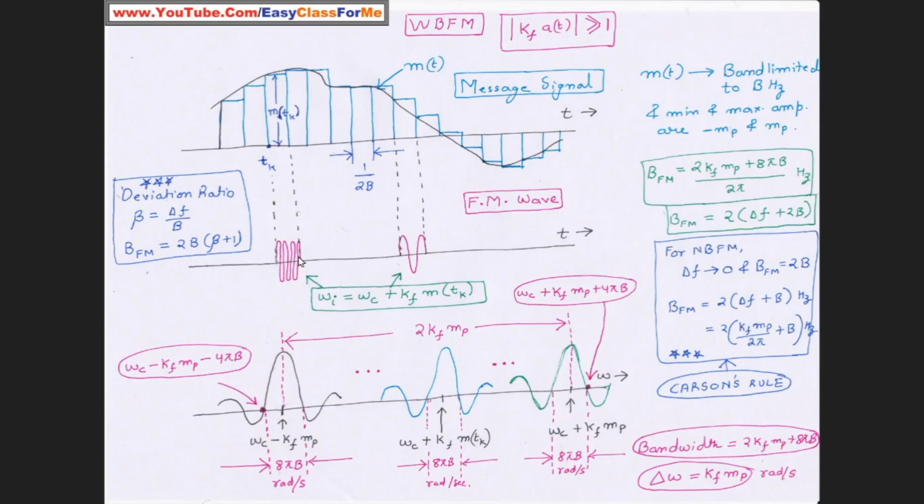We already know this from our discussion on amplitude modulated signals and waves, where we had a rect function, and if we take the spectrum of a rect function, it will be a sinc function, and that sinc will be centered around the origin. But if we multiply a sinusoidal signal to that particular rect function, then as per the modulation theorem, that sinc will be shifted to an appropriate frequency, the instantaneous frequency that you see here.